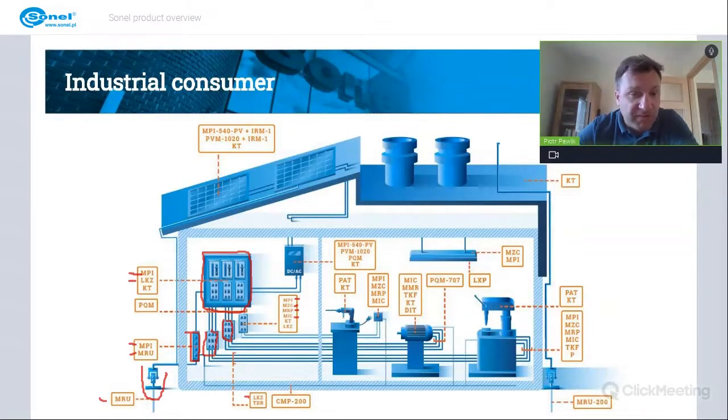Also, when we are talking about the cables, we can use a TDR, time domain reflectometer, to make sure that the cables inside are correct. So there's no break, there's no short, and we can see all the anomalies that happen in the cable. Also on the main switchboard, we can put a power quality meter. With this, we will know if the quality of the power that we are receiving from the energy utility is good, and what is going on in our own power quality network.